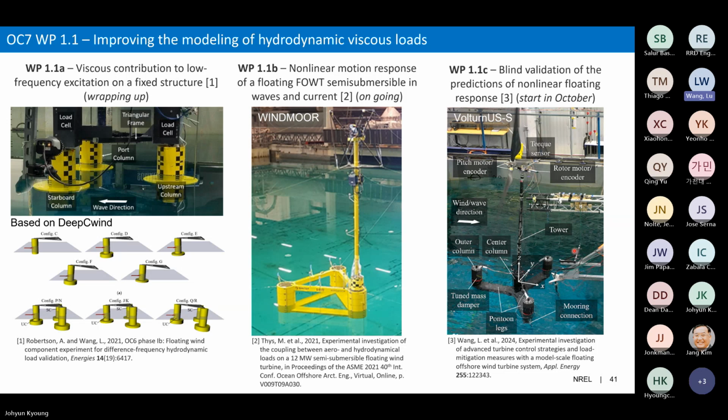So in particular, both of these designs feature rectangular pontoons not investigated in prior OC projects. So we're dedicating additional resources in the form of CFD simulations to study the viscous loads on the rectangular pontoons. So we only just started working with the Windmore platform in April, and we'll start with the Volturnus data set later in October, I think. Next slide.